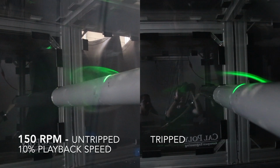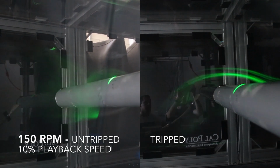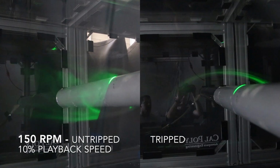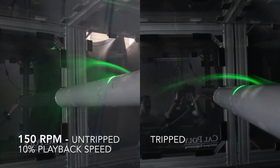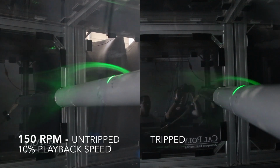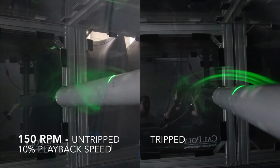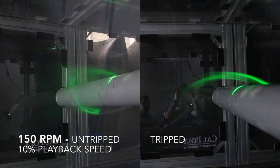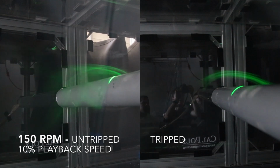For the untripped flow at 5 meters per second, we calculated a Strouhal number of about 0.07, and for the tripped flow, it was calculated to be about 0.03. The theoretical Strouhal number should be around 0.2, so these values do not make much sense. This is because it was very hard to observe the frequency at which the vortices were shedding off the cylinder.